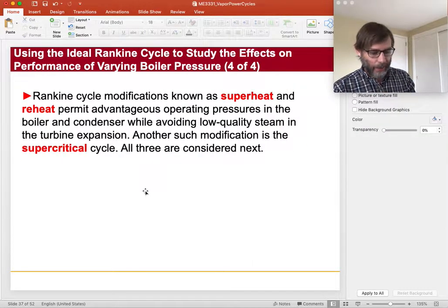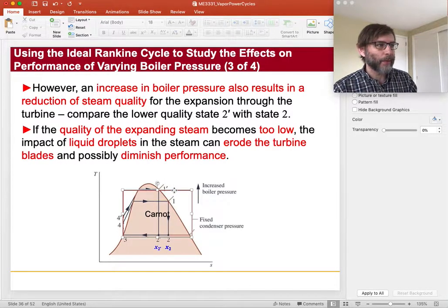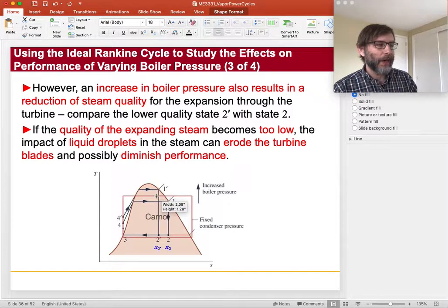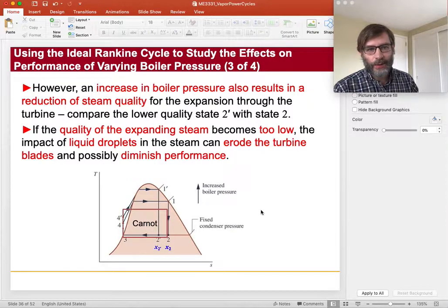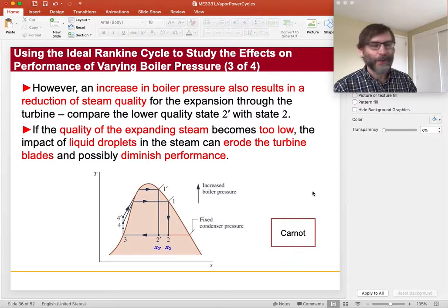You can say that probably you could take an average temperature, like here, and this would be your Carnot cycle. But what's the point of that, really? You can analyze a Rankine cycle pretty easily. So the Rankine and the Carnot are very similar, except that one piece in the boiler is isobaric and not isothermal. That hopefully answers people's questions. Probably confused the heck out of some people too. But I'm just going to treat Carnot as a box. I'll leave it on my slides, and I'll update those slides later.